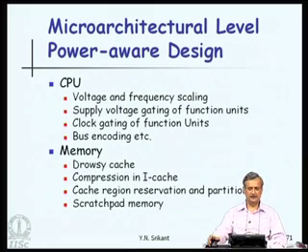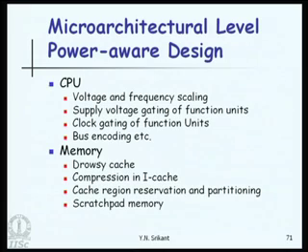Compression in the instruction cache is possible to save energy, because if we compress instructions, then the space occupied will be much lesser. So, the access will be faster and less energy consuming. Cache region reservation and partitioning, scratch pad memory, these are some of the techniques which are possible at the microarchitectural level.